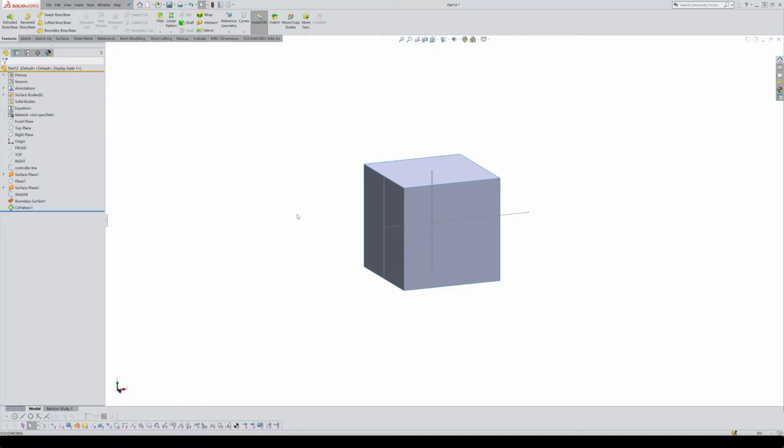Now there remains the issue of turning this cube into a solid. The fastest way to do that is to use the intersect command. Basically, if you have a collection of surfaces that completely encloses a volume, just like you see here, or in other words, it's airtight, the command will be able to turn that collection of surfaces into a solid. Sounds perfect, but we have to make sure that the airtight condition is met throughout our animation. So let's do a little bit more testing here.